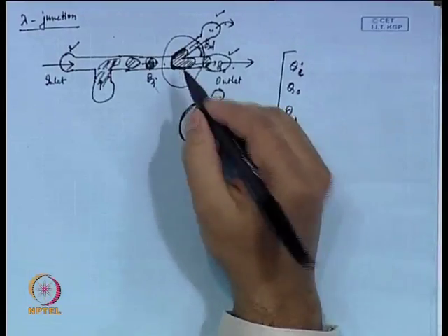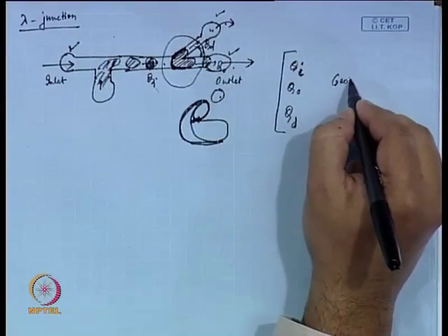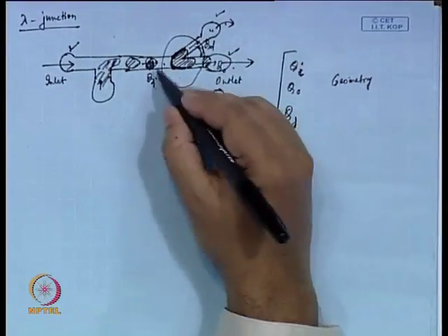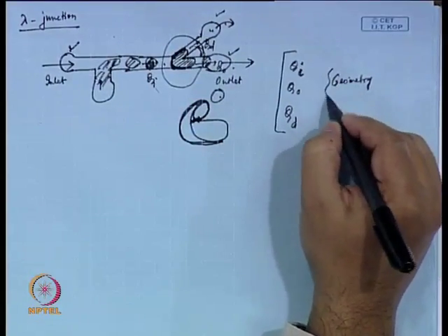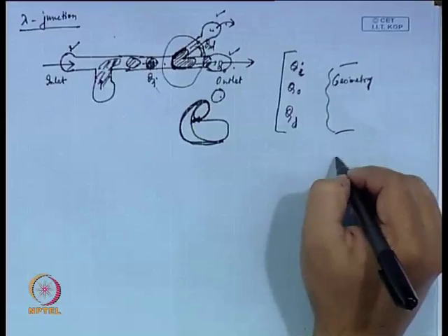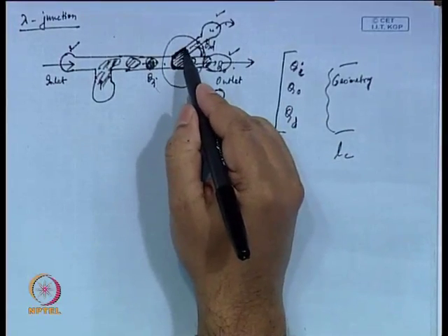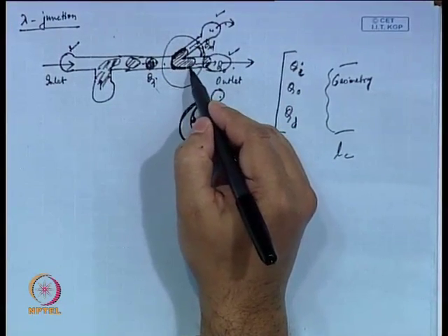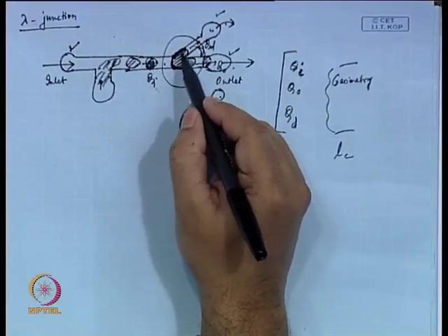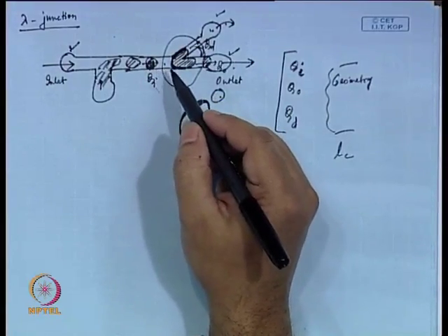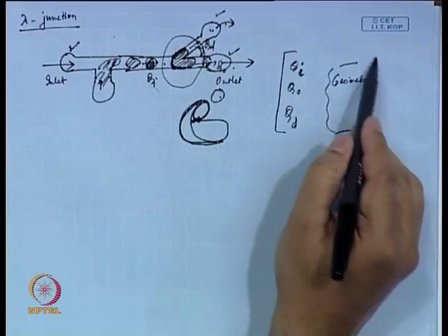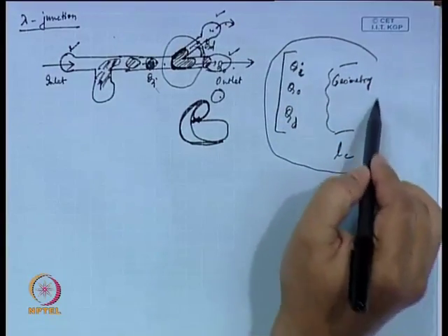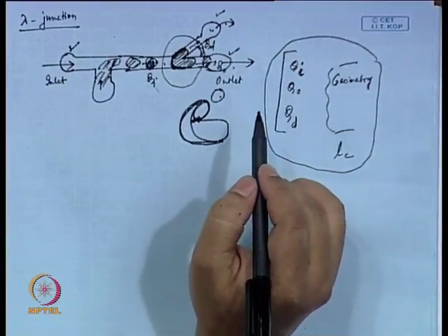So, other than these, what you need is geometry. That means, the dimensions of the channel, the angle and that delta, etc., that governs something called the L_C, up to what extent, what is the length of this back part of the droplet that has been stretched, okay, and that governs. So, these factors primarily, since you are in squeezing regime, you do not need to consider shear here.